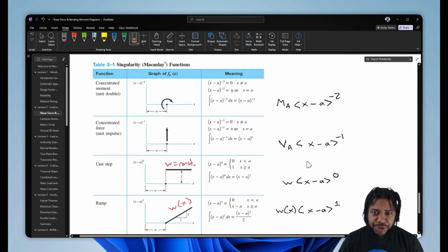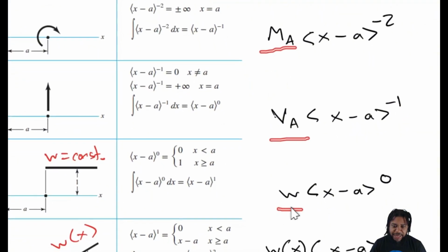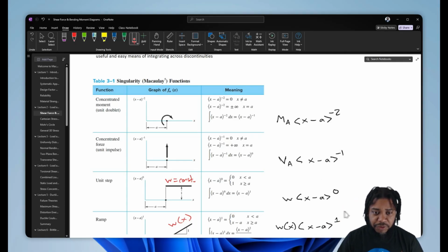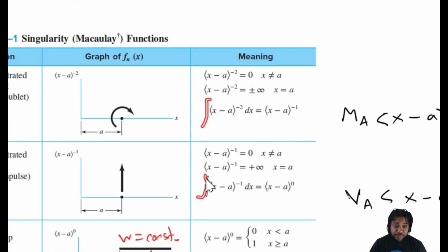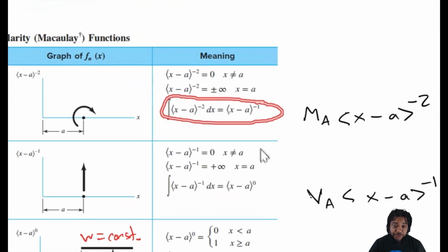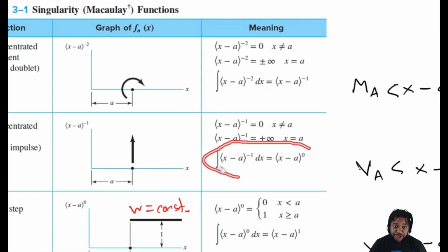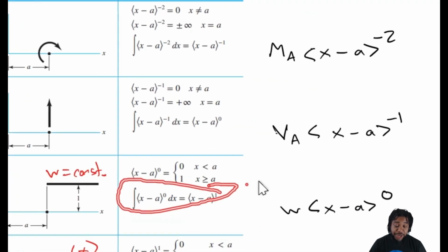So generally what we would do is if we're given some example with different coupled moments, applied loads, and distributed loads, we create a long form equation adding all of these terms together. And then we would integrate these terms. So once we have that full equation together, we would integrate using this form. It gives you the form of integration in order to solve for the shear force equation, and then also to solve for the bending moment equation.